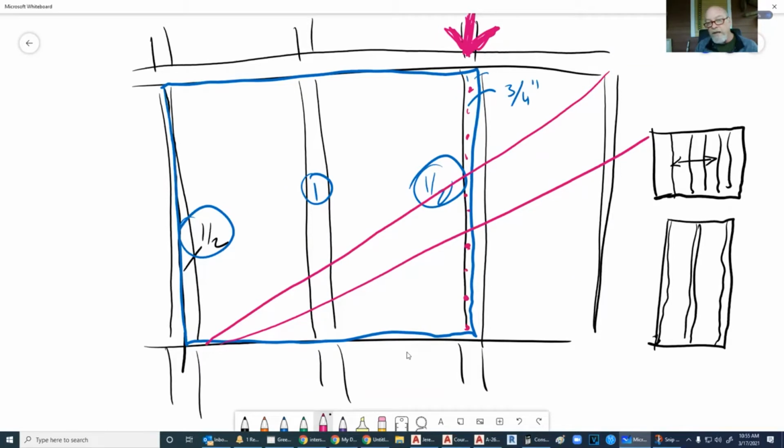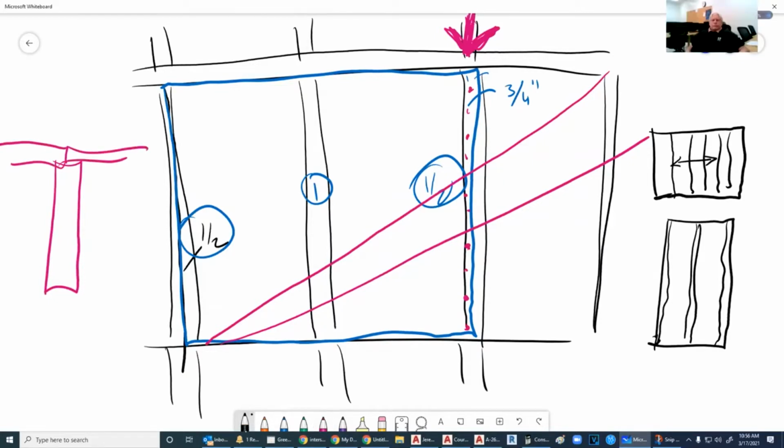on the center of a stud like this, a lot of times when this goes on, you have to really kind of come back a little bit and toenail that nail into it in that fashion right there. If you go too close, then it's going to tear out. It's going to be worthless. And I've done this on floor joists where I just nailed it in straight, and then I stepped from here over to another one and shifted this, and it tore out. I've had that happen many a time.